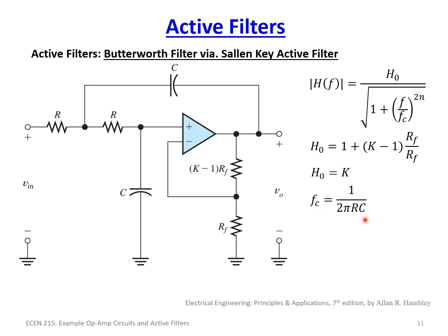And of course, the same applies. So we have our R and our C here, and the cutoff or corner frequency ends up being 1 over 2 pi RC. That's a good point here: this is a low pass filter, but if you wanted to turn this into a high pass filter, you just change the resistor and capacitor locations, and it flips.